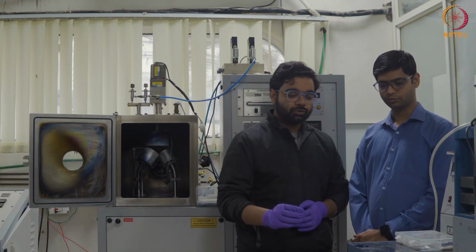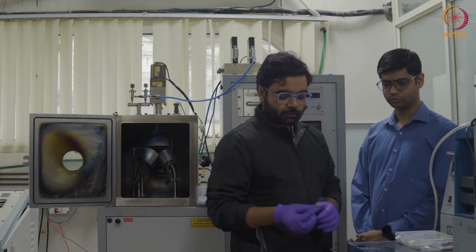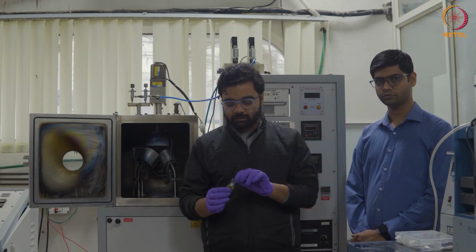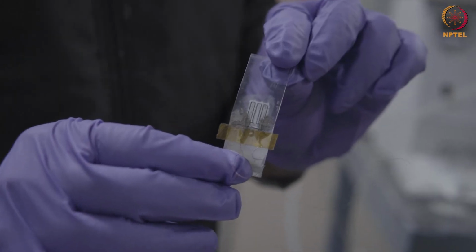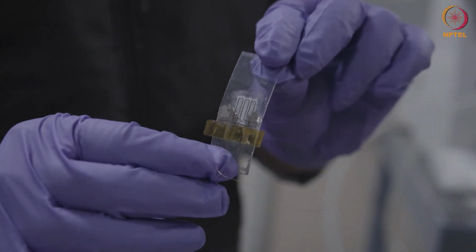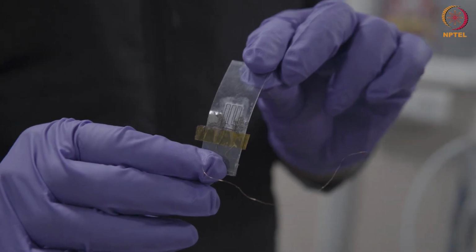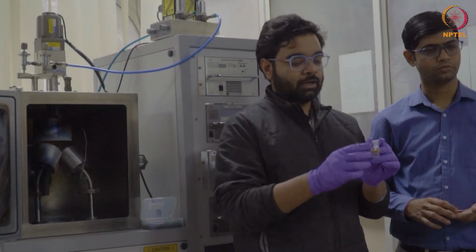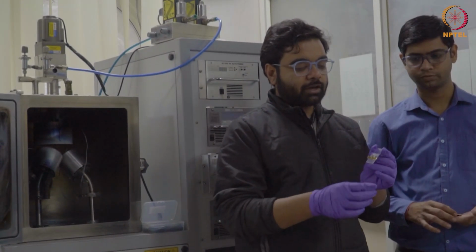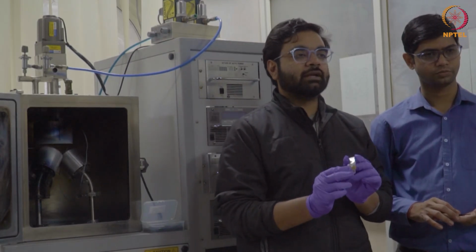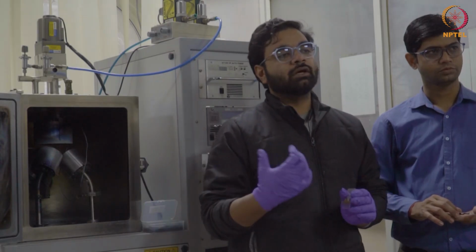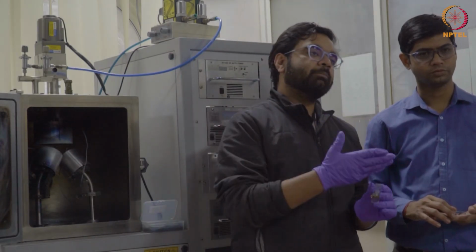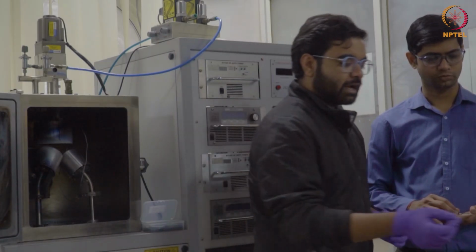I would like to show you a simple use case. If you could see over here, basically this is the strain gauge that we have printed. This strain gauge that you are seeing over here is a nickel titanium based strain gauge. We have printed it in a specific shape, connected it with copper wires, and tested its gauge factor. We tried to analyze how comparable it is with commercially available strain gauges and how much gauge factor we are getting. This is just a use case that we have used.